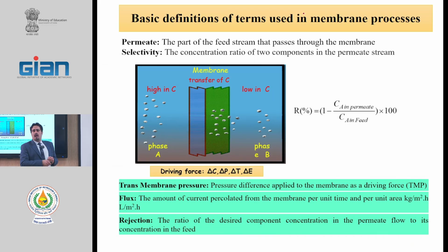For passing of the permeate through the membrane, we need a driving force, a force that pulls the solutes through the membranes. We generally have 4 driving forces: difference in concentration, difference in pressure, difference in temperature, and difference in electric potential.